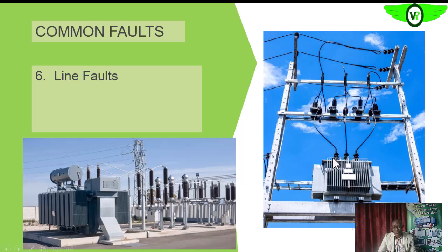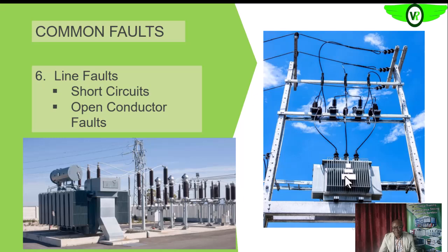So if we have problems on any of these lines, assuming we have a short on the line, what we have succeeded in doing is shorting the transformer winding also. That can result in a very high, excessive current event that can burn the transformer winding, cause deterioration of the insulating materials used for the transformer, and other faults. That can result in short circuits, and at times, if the arcing is high, it can cause the burning and eventual breaking of that conductor. That will cause open circuits, either within the winding or on the line. If it is within the winding, that can cause the decommissioning of that transformer in the system.